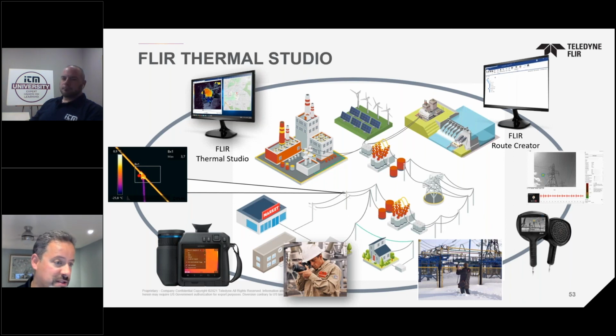But we also have vibration sensors. The best thing to do is install specialized vibration sensors on the motors. They're wireless, and they transmit 24 hours a day for years. If anything is out of balance, it checks the 3 axes, X, Y, Z, and you'll see it in the graph. You can even do an RPM calculation to see what the motor is doing if something's not right. So there's a lot available. Today we just focus on acoustic and thermal, but we have other types of sensors as well.